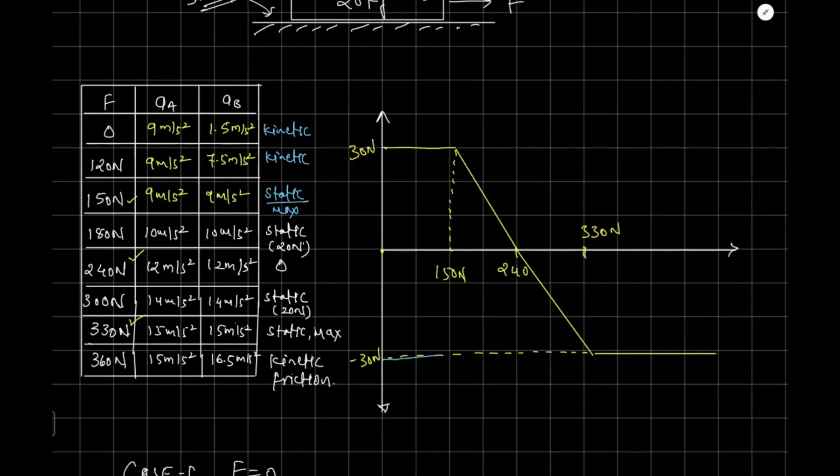Initially, the friction force that was acting is negative. Then it will start decreasing. Then it will change to positive, and then it will become constant because we are going to have an action-reaction pair. So when it's an action-reaction pair, it means every time this value must be equal. Which value must be equal? This value. So suppose this point and this point are lying on the same line. If this value is 20 Newton, this value must be minus 20 Newton in that case.